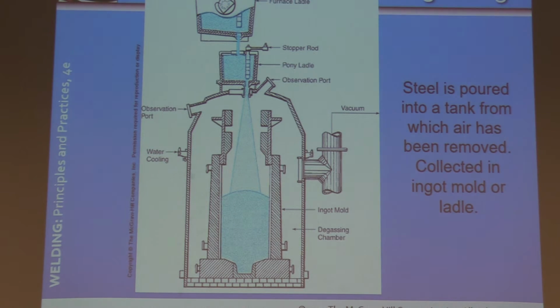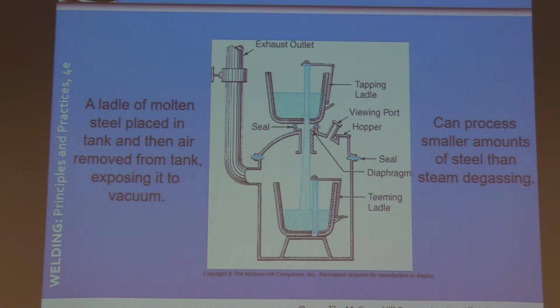Page 60, bottom left. Ladle degassing facilities of several kinds are in current use. In the left-hand facility, molten steel is forced by atmospheric pressure into the heated chamber. Gases are removed in this pressure chamber, which is then raised so that the molten steel returns by gravity into the ladle. Since not all the steel enters the vacuum chamber at one time, this process is repeated until essentially all the steel in the ladle has been processed. Quite an interesting concept.